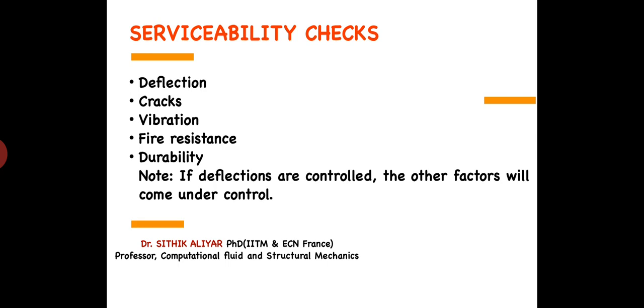After that incident, all the code books throughout the world have been revised to include a section for fire resistance. Then there is the durability check, how long your structure should be durable. These are the serviceability checks you should do, depending on your concern. Mostly, if you keep the deflection under control, all other factors will come under control. We will see more from the exam point of view, so we will concern ourselves more with the deflection.